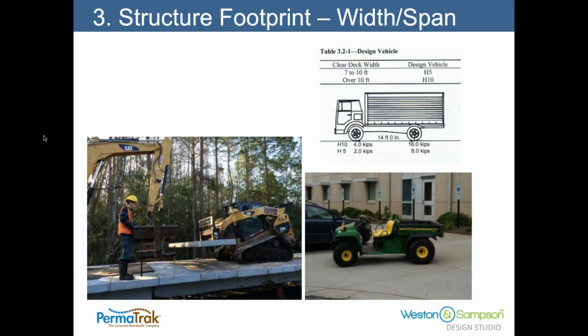Another consideration is as you make the boardwalk wider, the load requirements are increased. And in the top right-hand corner, I've taken a section from the design code. And the design code for boardwalks is the LRFD Pedestrian Bridge Guide. And currently, there is not a section that will tell you how to design a boardwalk. There's not a section in the bridge guide that tells you how to design a boardwalk, or even in the building code. So the best design resource out there is the Pedestrian Bridge Guide.